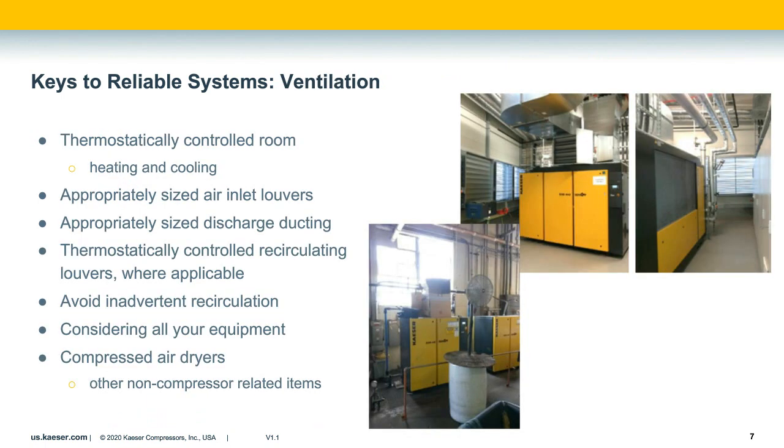When I mentioned typical compressor failures before, temperature was at the top of the list. So ventilation, both cooling air inlet and cooling air discharge, is going to play a large role in how your compressor operates. If inlet louvers aren't large enough, you end up with a negative pressure in the room. So what happens is, if you're trying to walk into the room and you're opening the door, and the door is a swing-out door towards you, as you open the door you have significant resistance, and air is just being whooshed past the door trying to get in. So that's difficult to do.